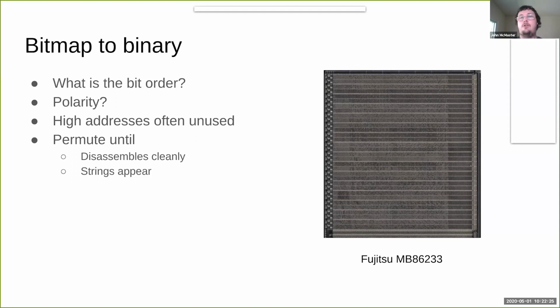The second is, if you're familiar with the disassembly for this particular architecture, you might be able to do some heuristics. For example, for 8051, a lot of times they start with a jump instruction as part of their vector table. Most commonly, this is 02, sometimes 01. And I think you'll find on most embedded architectures, there are similar patterns to look for.